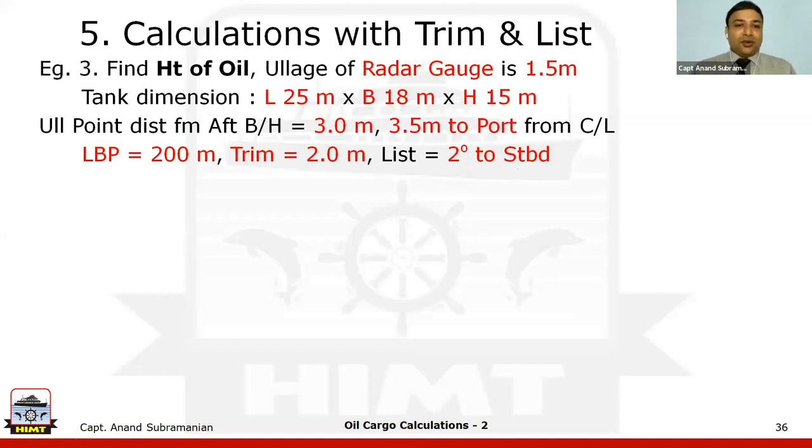Okay. So even if you don't bother to draw a diagram, at least you can get the values directly from there, and then you can get the answers. And I only want the height of the oil. If you find out the height of the oil, the rest is very simple. From the height you find out the ullage, from the height you find out the volume, and from there so on. That's a very simple part. But here, what we want to find out is the ullage, and from the ullage, the height of the oil.